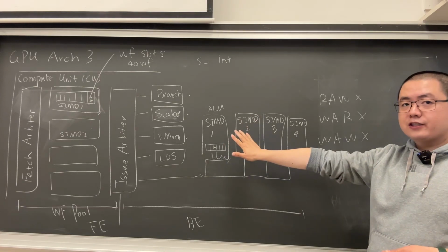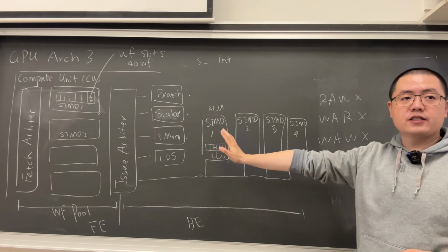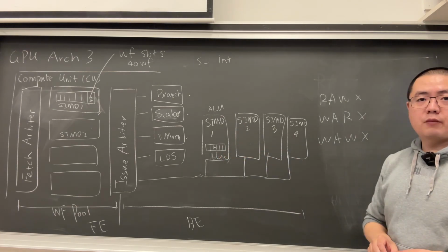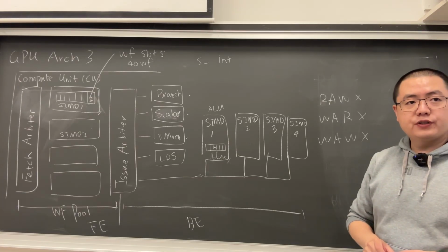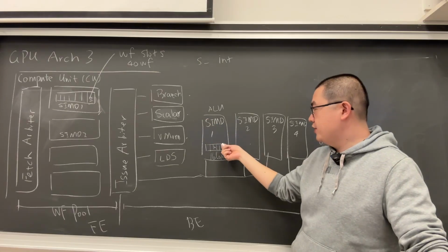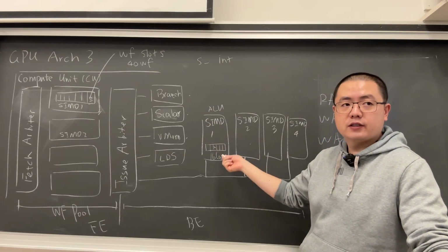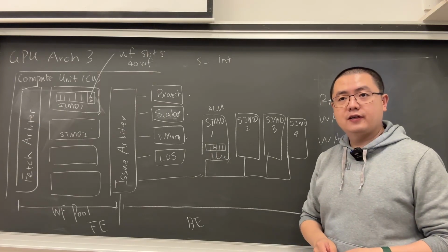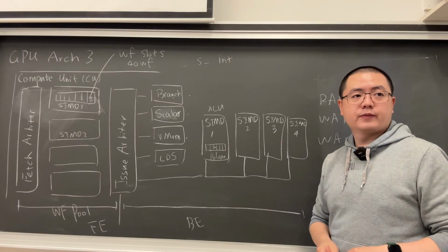Now for NVIDIA GPUs, I know from a very early stage, this is not the case. NVIDIA has this double issue. Why? NVIDIA wants to take the opportunity: I have an integer unit, I have a floating point unit. Then if I have an integer instruction and a floating point instruction, I can use the pipelines at the same time to improve the performance.